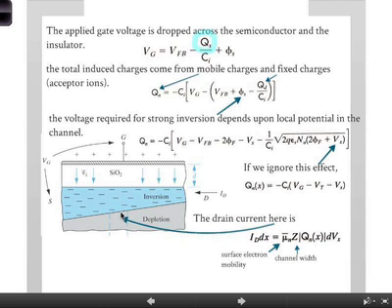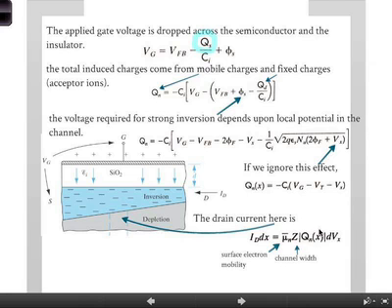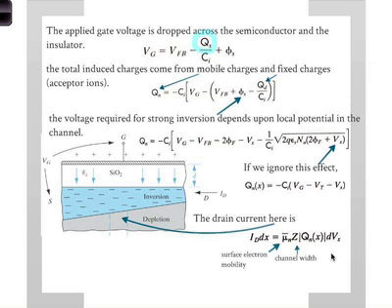You plug that in. So in this case, the drain current at some location x here is given by the mobility of the electrons. I'll come back to what that dash is in a second. Times the number of electrons, where Z is the depth out of the screen, times the charge density, which we just talked about right there, times dVx over dx, which is the local electric field. Yes? And they just do absolute values so that it's non-directional?